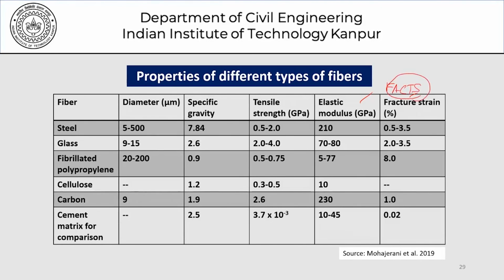Now we need to understand, evaluate these facts on the basis of strength per unit weight. We have not listed cost, which could be in tons or rupees per ton or dollars per ton. Now, if we want to compare the performance in terms of cost, in terms of weight, we are very much free to do that. So I'm leaving it to you as an assignment to find out the cost of these fibers in your neighborhood and try to then understand and evaluate how we can go ahead, or whether as an engineer we should go ahead and use fibers in concrete.